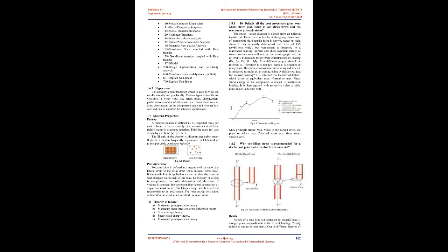If element size data of meshing is not specified by the customer, a convergence study is conducted to determine element size. Care should be taken to decide the type of element to be used, like 1D, 2D, or 3D elements. Special considerations have to be taken while deciding the elements at welded regions, solder joints etc., with a focus on engineering productivity. HyperMesh is the user-preferred environment for solid geometry modeling, shell meshing, morphing detailed models, setup of surface geometry modeling, automatic mid-surface generation, and batch meshing.